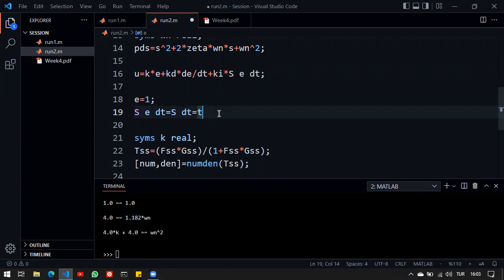And that's a bit problematic. So, of course, if I have a finite value, then this will also be finite. If I'm using an integral part in my controller, then ideally what I want to end up with is that the error should tend to 0. If error tends to 0, then this term will be constant, because the integral of 0 dt is constant. So the integral action here is fairly important, and we'll see.